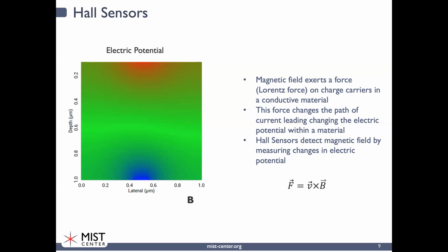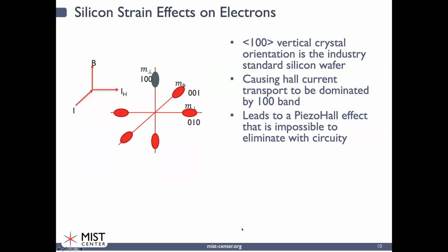So one of the things that we've been investigating with Texas Instruments, and Thomas Weingartner has been leading this work, is to take a look at how mechanical stress can change this as well. So when one stresses the crystal, the 6 conduction band orientations in silicon get changed. Their shape changes, and this is a basic piezo effect. You know, think about changing the tension on a string in a guitar. You get different vibrations, and the fundamental notes change.